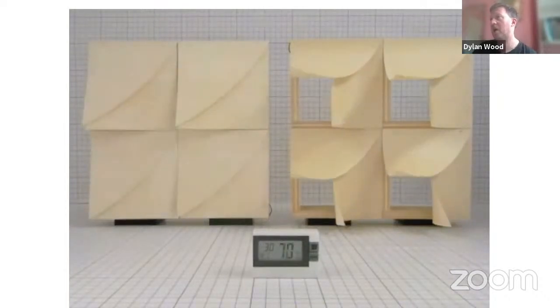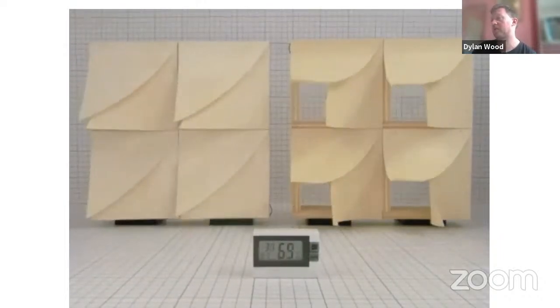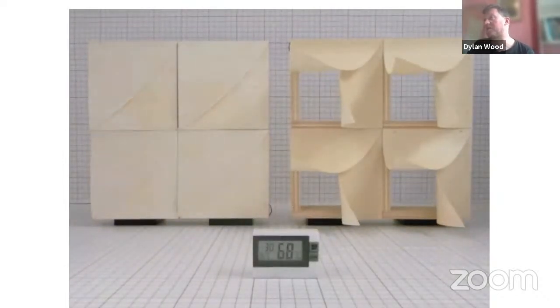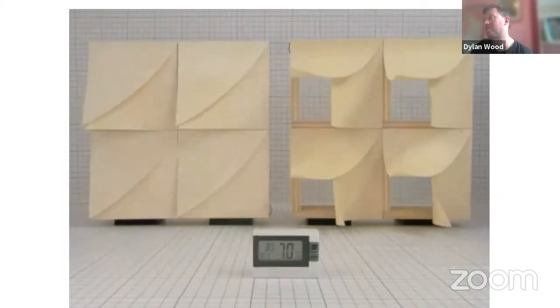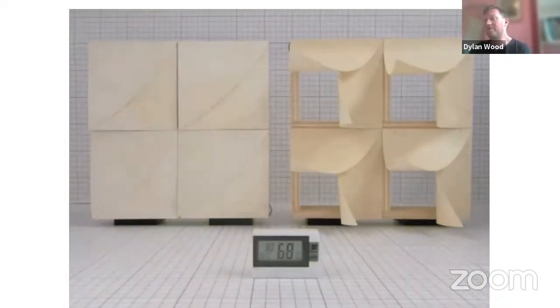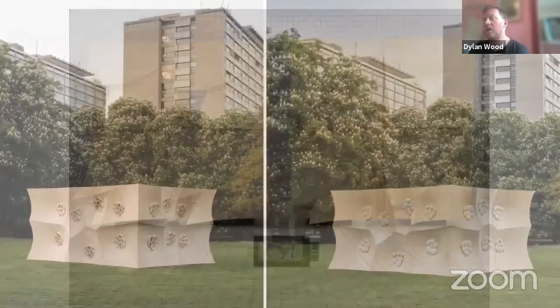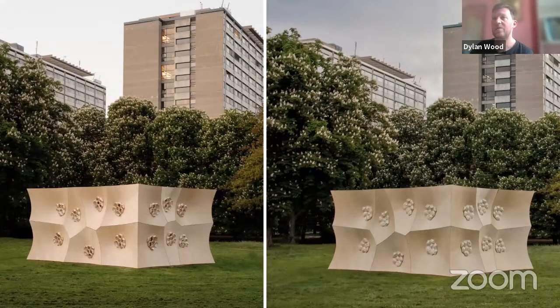So something like what you see here, where we can build up parts that respond by curving when they're exposed to different weather conditions. And the programming here happens through the physical composition and the mechanical design of the parts, or the composites, in order to be able to program them to respond in specific types of movement patterns under specific stimuli. And this is something that we tested already in these types of prototypical architecture, like the Frac pavilion, where the apertures are designed to open up when it's sunny and then close up when it's raining.